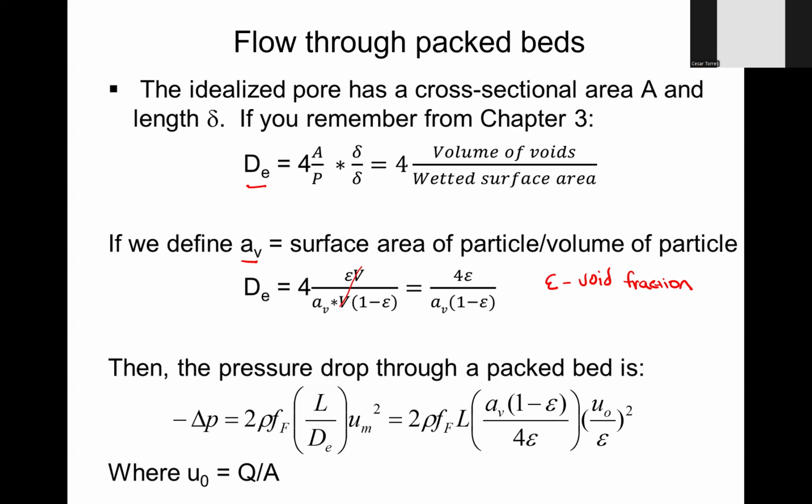Now we're going to take that and use it in an energy balance. Now, remember that with this packed bed, and this is the first disclaimer, we're using a packed bed that is horizontal. And when that packed bed is horizontal, we will not have a delta z in our energy balance. The velocity on one side or another is the same. So u1 equals u2, if this is 1 and 2, and z1 equals z2, which means that at the end, what you have is a pressure drop related to a frictional loss.